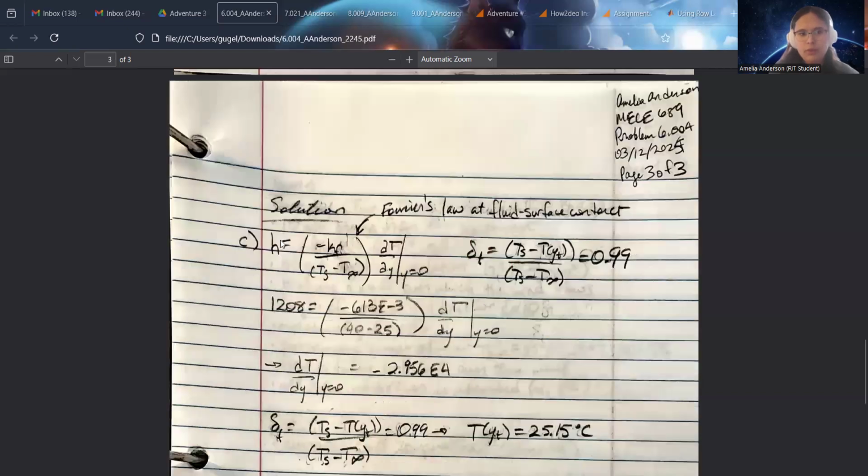So now for the boundary layer, this is an equation you can find in the textbook. It's sort of approximate, sort of not really. You can represent, actually represent is a better word to use here than approximate, the fluid layers that are very close to the surface as if the heat flow is due to conduction in the fluid as opposed to convection within the fluid.